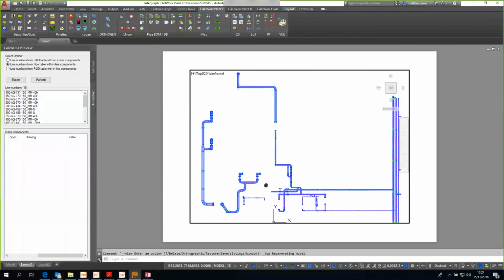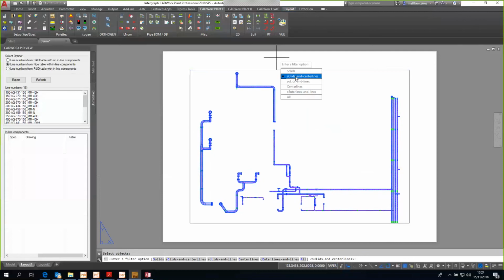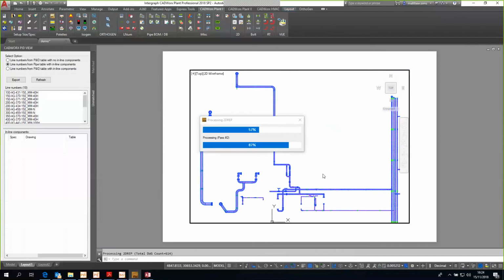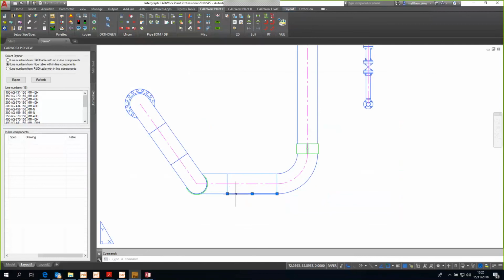You could do a drawing out of that, but if I use 2D Rep, I'll do it for the viewport, so it'll just do everything inside here. Solids and center lines. So all we'll see is the solid, no hidden lines, and just the center line. So if I run this on the drawing, it only affects the view we've got in this paper space. So the model has been left unaffected, but now it's lost its intelligence. So now it's just AutoCAD lines, arcs, and circles.